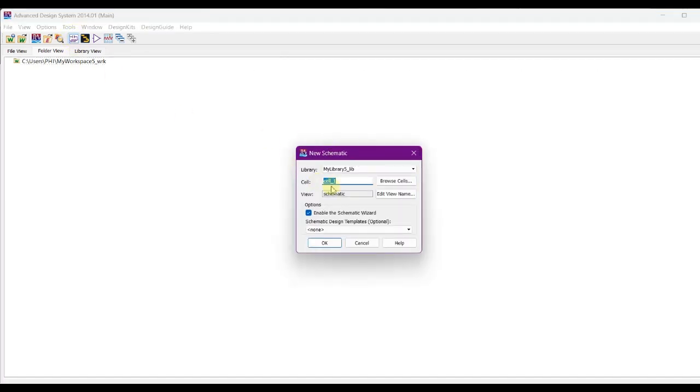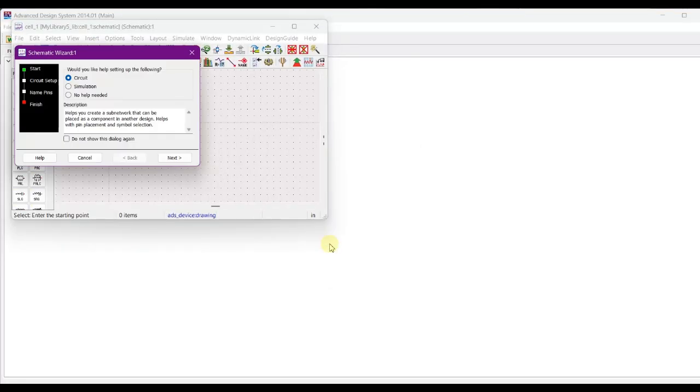We will create our equivalent circuit model in ADS software, that is Advanced Design System, and its version is 2014. When you open ADS and create a new worksheet, you will find this kind of screen. Now just click on the schematic diagram. When you click on schematic diagram, it will ask for your file name.